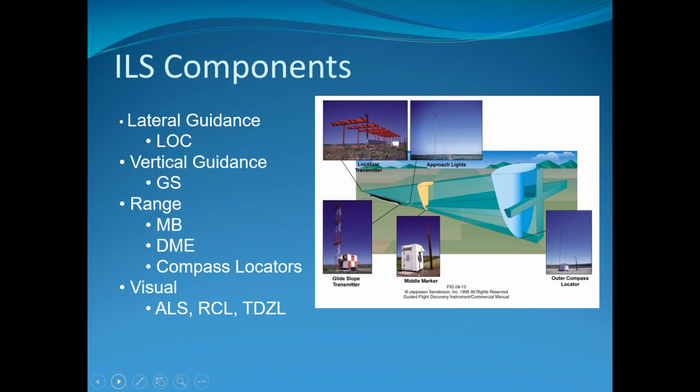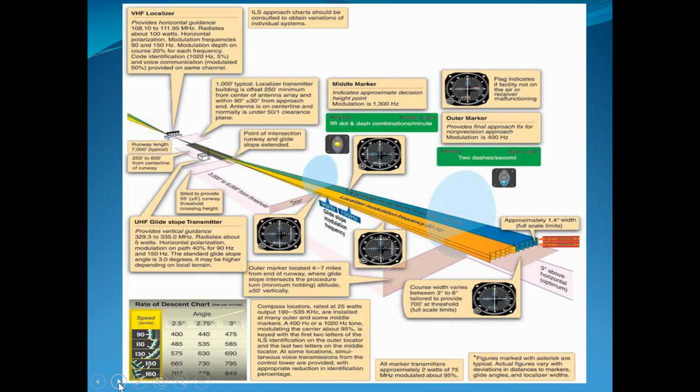So let's look at the next one here. This is still looking at ILSs, giving you a further outline of how it works. What you need to know is what an ILS is and that it gives you both horizontal and vertical guidance. You don't need to necessarily understand the system itself and all of the technology behind it. You just need to know that it's ground-based, it's a precision approach, and then know those Category 1 minimums, the 200 feet and the half-mile visibility.